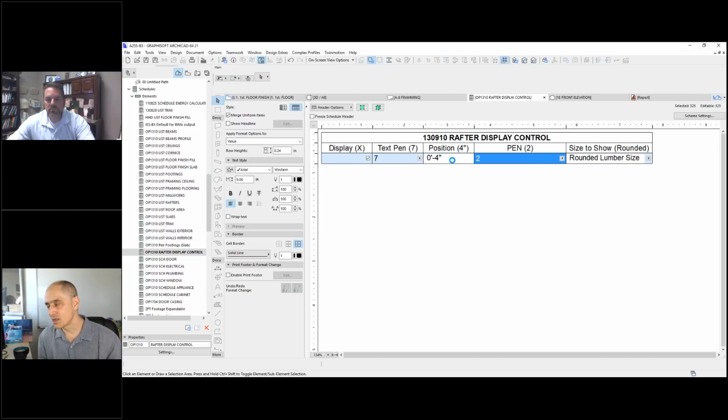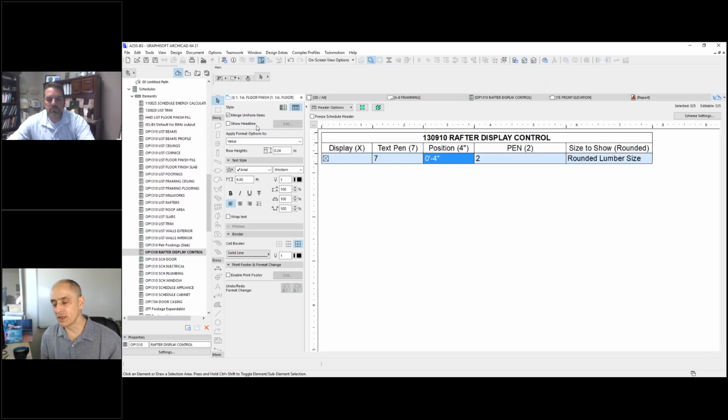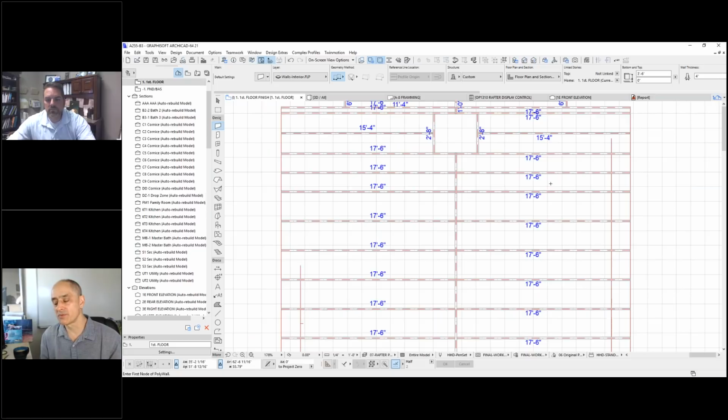Just as an explanation to everyone watching, what Chip's doing is he's running a schedule. So if you just hold for a minute while I explain it, because I think it'll help people to understand. When you run a schedule, frequently you're saying, list every element, every door, or sometimes you say list certain windows together, like there are 4 of these type windows and 2 of those type windows, so you group them together. Now the grouping can be based on a variety of criteria.